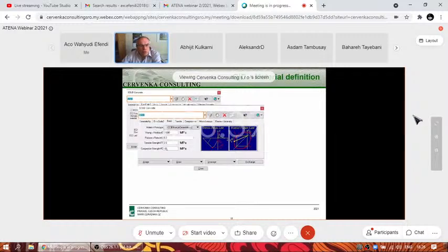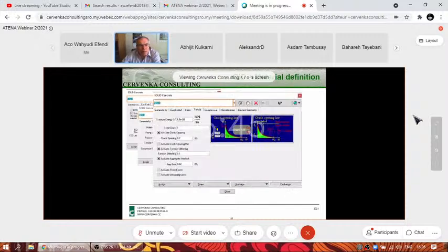It then generates some basic parameters like modulus, Poisson ratio, tensile strength, compressive strength, tensile properties. Important parameters there are fracture energy, fixed crack, whether we have a rotated or fixed crack. Crack spacing is an important parameter where we have large finite elements. So in this case, we can expect that there will be more cracks inside one element. So it is important to find this crack spacing.